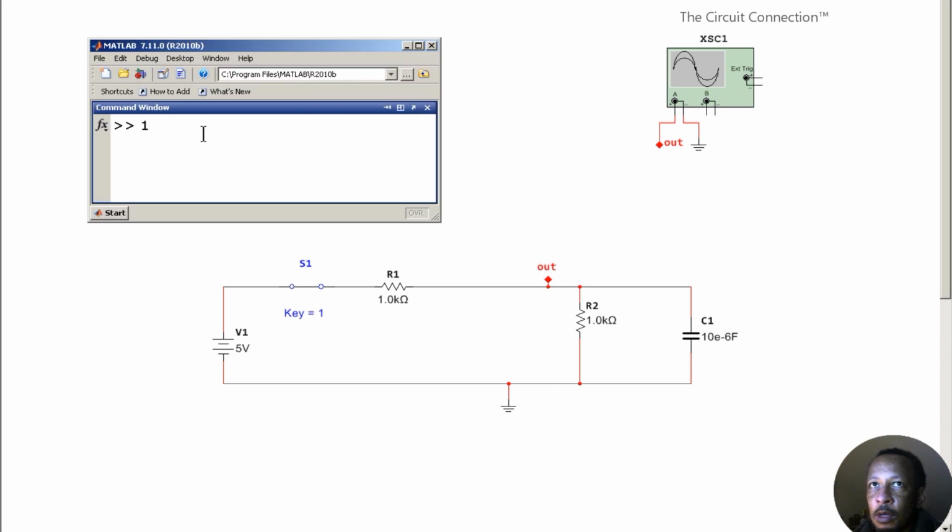So during your charge up, you're going to have 500 ohms times 10 microfarads, and you're going to multiply that by 5, because by 5 time constants' worth of time, any transients have basically come to their settling point, all your transients are gone in the circuit, and it's going to be settled by then. So that gives us 25 milliseconds to take a look at this on its way up when it's closed.